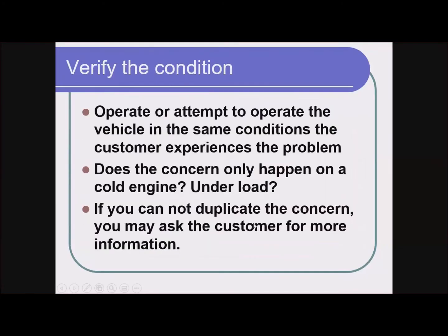So this goes right back to that statement, verify the concern or verify the symptom, right? So you have to know what it is you're trying to fix. If you don't know what you're trying to fix, how will you know when it's fixed, right? If you've made no change, you won't know when it's fixed. So verify the condition we just finished talking about. Attempt to operate the vehicle in the same conditions the customer experiences the problem. Does the concern only happen on a cold engine, only under load, etc.? If you cannot duplicate the concern, you may ask the customer for more information or have your service writer do that.